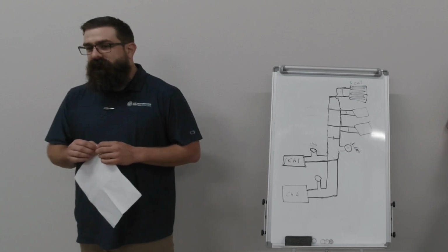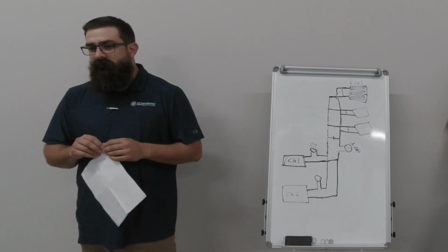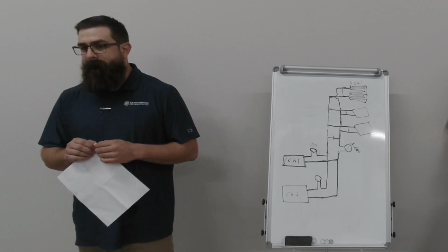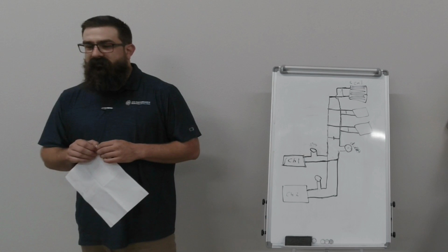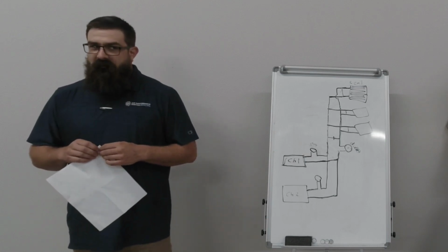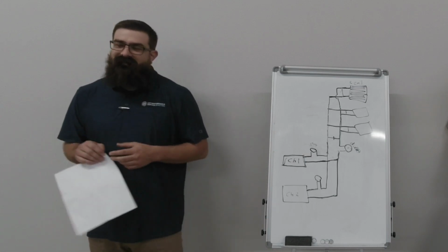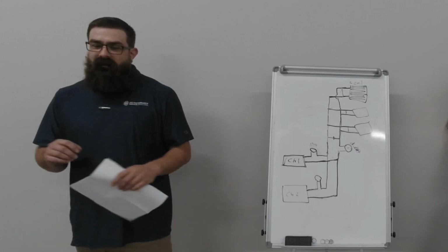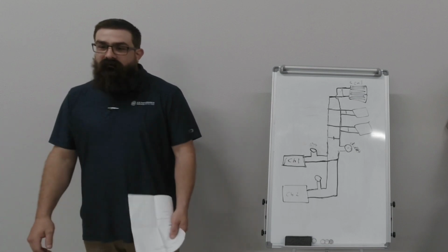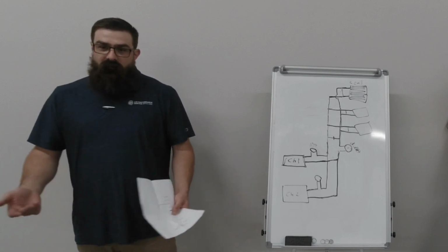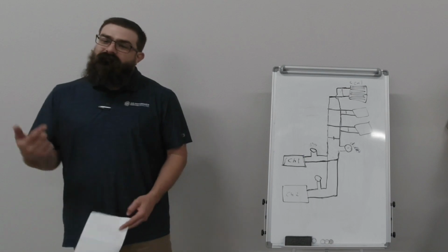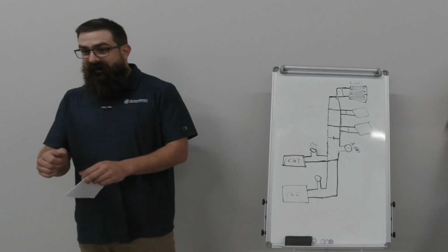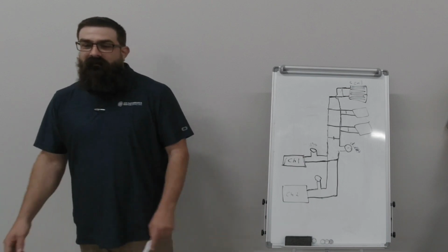No questions? No answers? Primary's moving the water to the children, and secondary moving the water to the... Yeah. Typically. I mean, I've seen them labeled other ways, but as long as you know it as primary, secondary, it matters what they call it in the building at that point. Because the one building I deal with here that has it is actually flip-flop. They call primary the building and secondary the chillers. Whoever decided to put the label on it, that's just what they did.